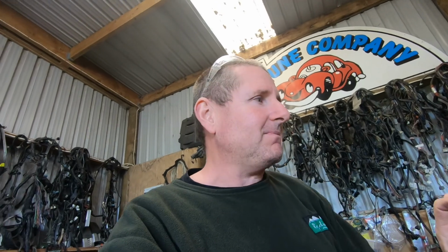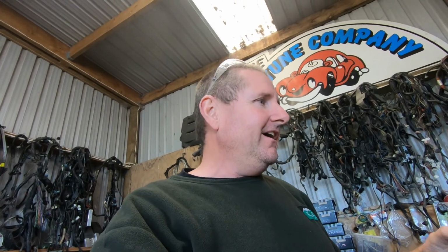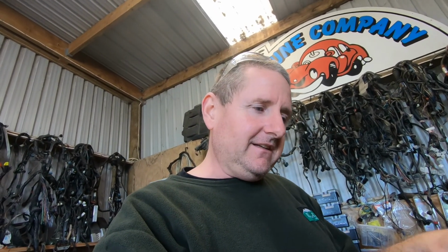And this is one of the reasons I see these cars sitting around not running or not diagnosed, because of this fault. Or conversions that have just been wired up and they just haven't pushed the coil connector on properly, or it's got a shitty connector, or the front crank loom connector that goes down to the coils has got corrosion in it. All those things can cause these codes. And it happens on the non-OBD2 as well in the LS400s, but it doesn't always throw a code. But it won't start the engine. It'll just fire and stop, fire and stop, fire and stop.